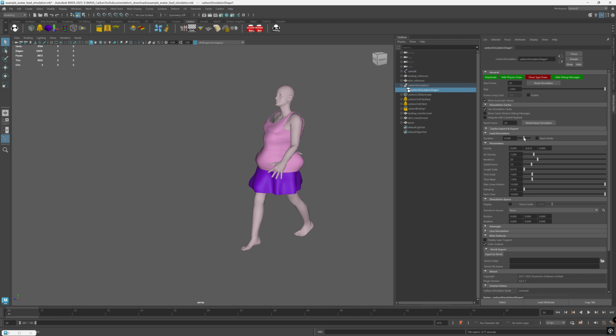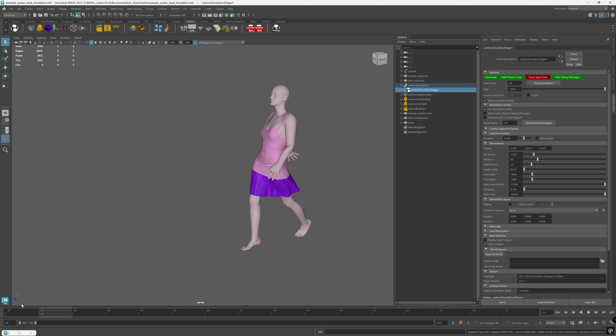Lead simulation runs an optimized simulation interpolating between the start and the reference metrics of all objects and all constraints. So for example here, cloth and binding. What it does, it allows you to go in one frame from something like this, for example, to something like this. It's an optimized version, so it should be faster and happening under the hood. You do not have to actually store the intermediate results.